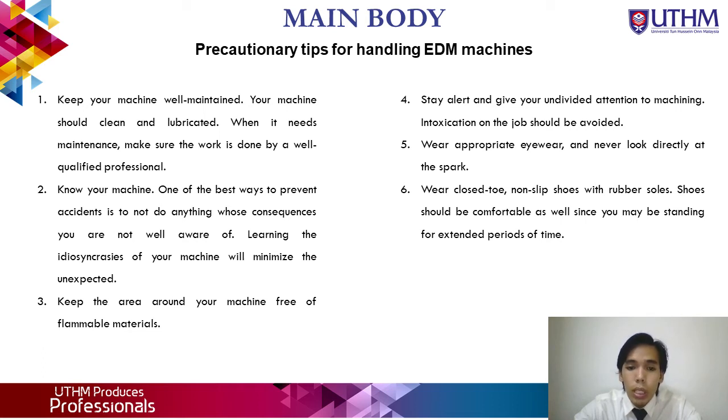Fourth, stay alert and give your undivided attention to machining. Fifth, wear appropriate eyewear and never look directly at the spark. Sixth, wear closed-toe, non-slip shoes with rubber soles. Shoes should be comfortable as well, since you may be standing for an extended period of time.